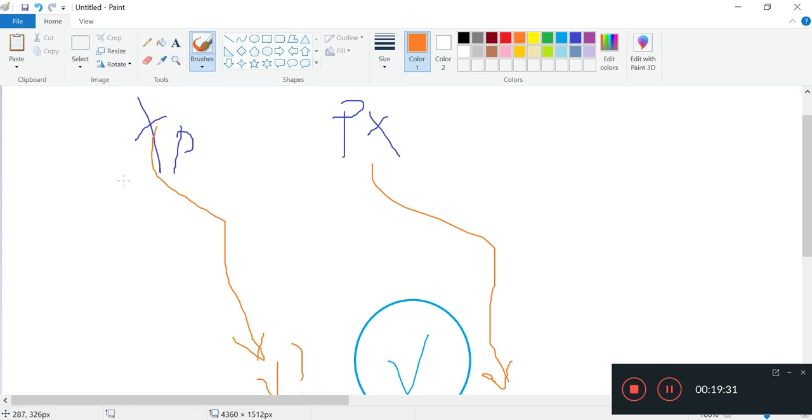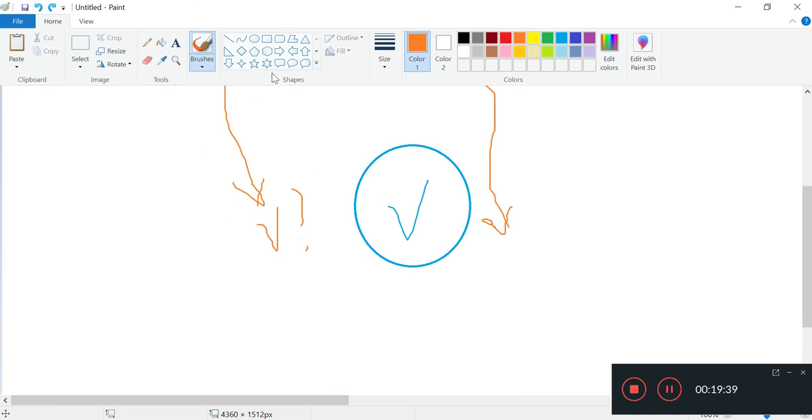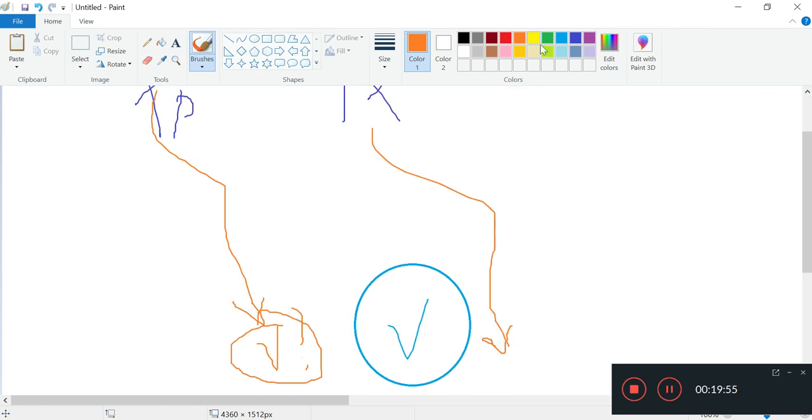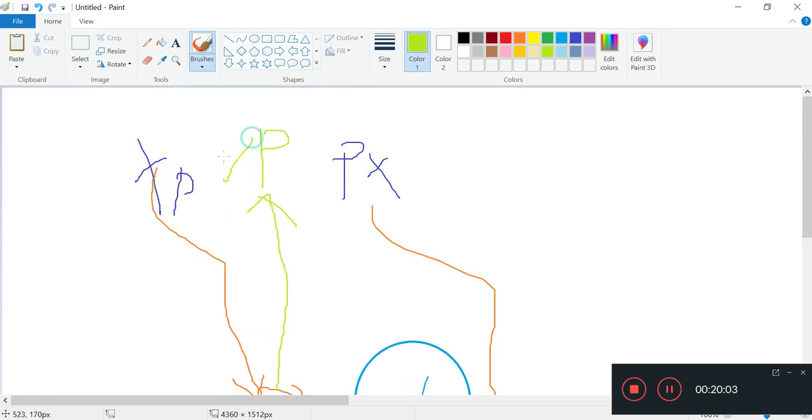So the problem is we need a new guess for the pressure field based on the feedback that the continuity equation gives us. Unfortunately, in this form, the continuity equation will not give us any kind of feedback on what our next guess of pressure should be. Ideally, we want feedback to say, based on this new velocity field, what is my next guess of the pressure field? That is something we need, and we can discuss more of that in the next video.